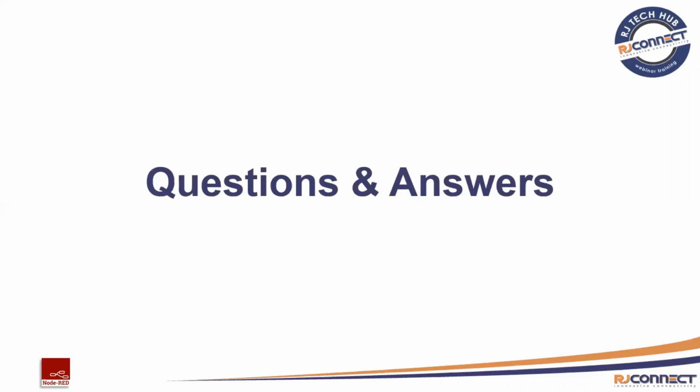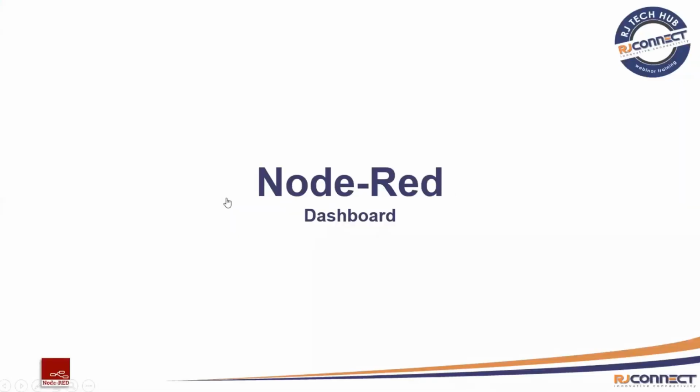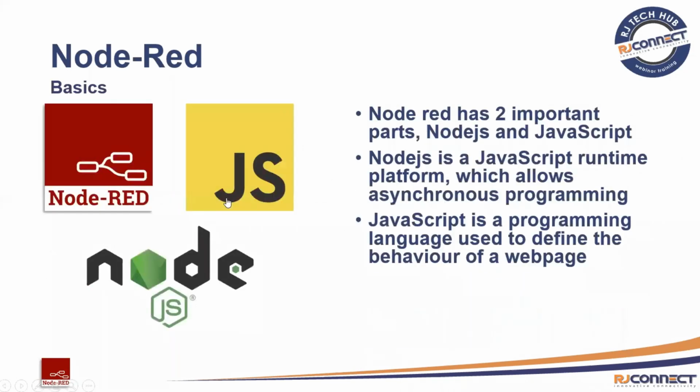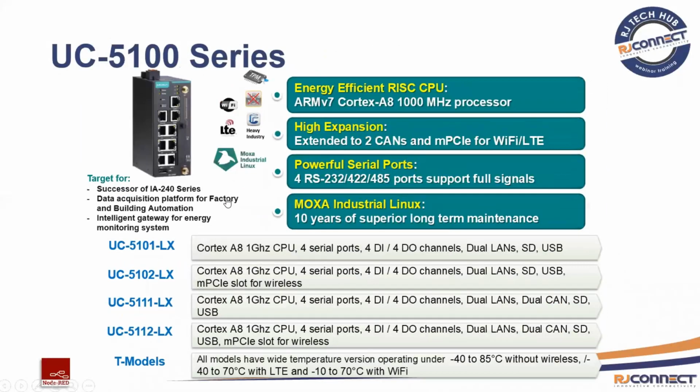On the previous slides, you showed a couple of hardware that runs NodeRED. Yes, on those slides. And I think some of the hardware that you showed have input and output signals. Yes, like this one, for example. We would be required to develop a node or develop the code to access this using JavaScript, because Moxa developed the code with C and Python. So we have Python examples of getting to these digital inputs and outputs, but we don't have JavaScript examples. So we need to develop that code to be able to access that in NodeRED specifically.